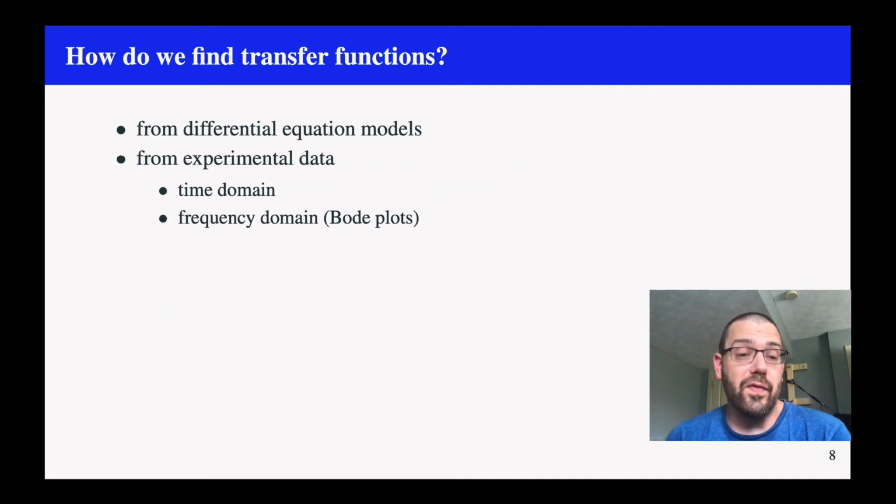So, if transfer functions are so powerful, and they are, and we're going to use them throughout the course, and they're going to do lots and lots of great stuff for us, how do we find them? And so we're going to talk about two main ways in this course that we're going to find our transfer functions. One is coming up with a differential equation model. That's going to use things like what engineering professors like to call first principles, either Newton's laws or Kirchhoff's laws or whatever, to come up with a differential equation model for whatever system we're talking about.